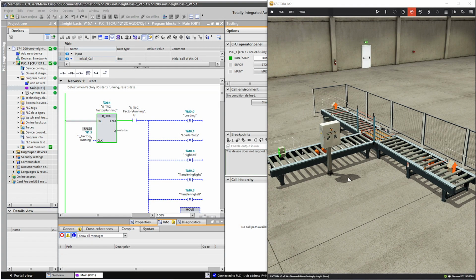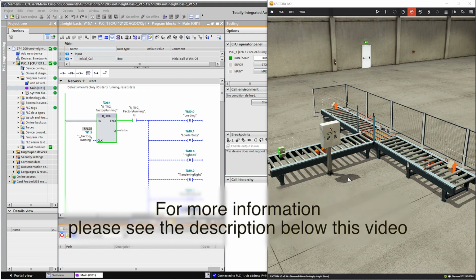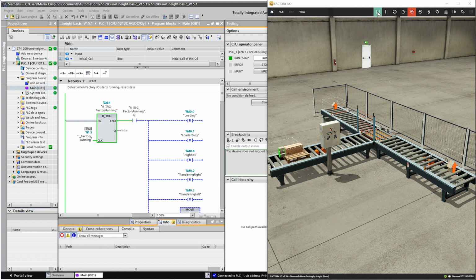Welcome back. So let's get straight to it by restarting FactoryI and see what we're trying to achieve before we then close the PLC program and start coding from scratch. Now, the entry conveyor starts emitting boxes of different heights completely randomly, and the height of each box is detected by the light array emitter, beam if you like. Then, depending on whether a box is large or small in height, determines whether they are transferred either left or right. As you can see from the simulation, the larger height boxes are being transferred right, and the smaller height boxes are transferred left.